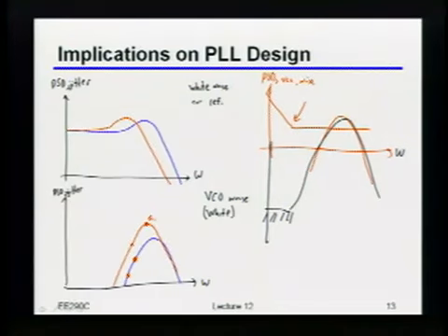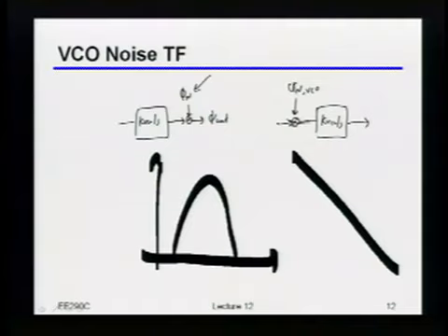Why is this not zero? Because isn't it with reference to the center frequency of the VCO? No, because again, I'm drawing the spectrum of the equivalent voltage noise going into the oscillator. Right, going into the control terminal of the oscillator. So if I have DC noise here, like if I have a DC shift in the voltage there, that would mean that my DC frequency has shifted. Does that make sense, or?